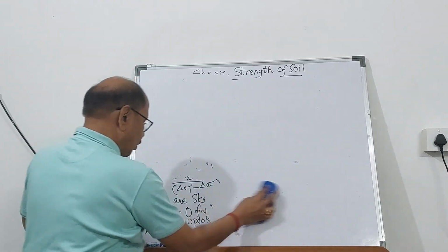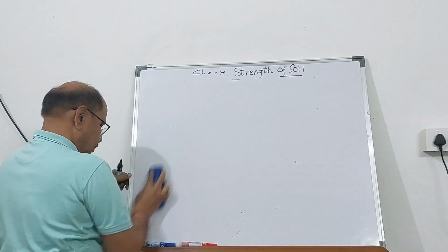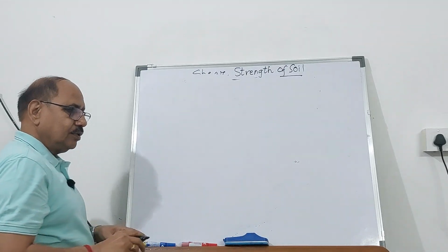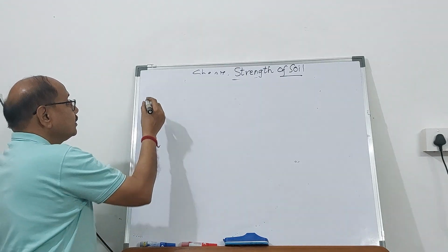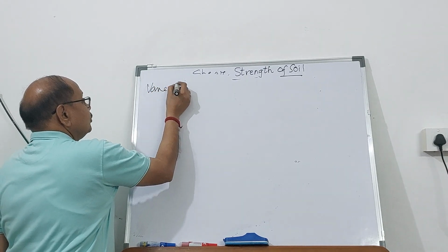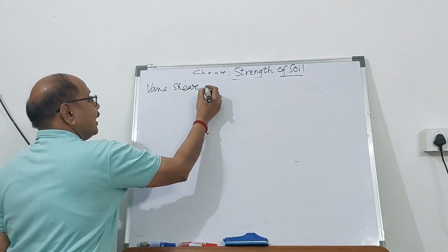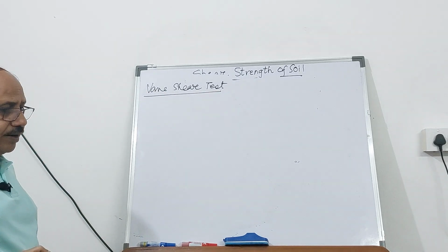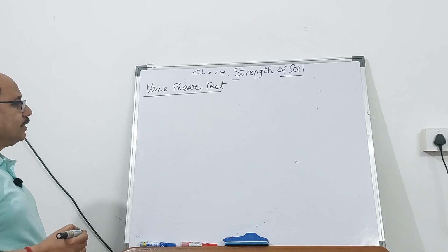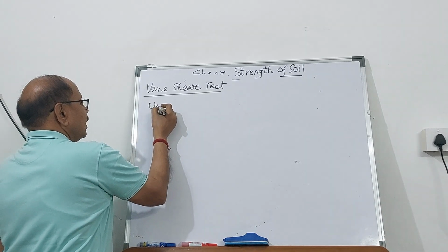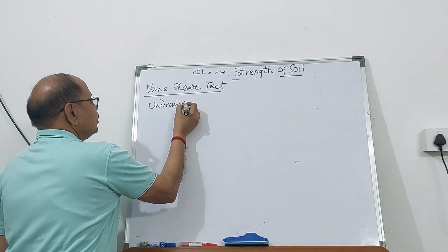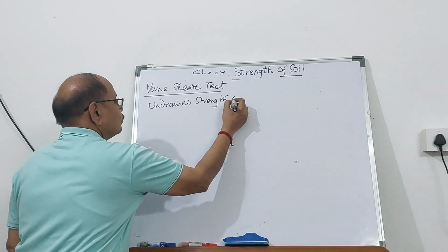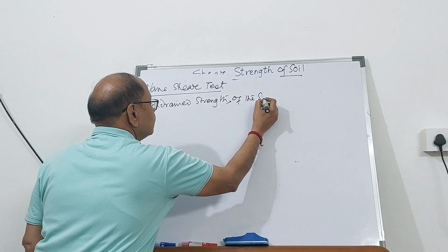Then all the tests, right from the triaxial test, box shear test, Vane shear test. Vane shear test is also very important. You know, Vane shear test for soft clay, we carry out the Vane shear test and try to find out the undrained strength of the soil, soft soil.